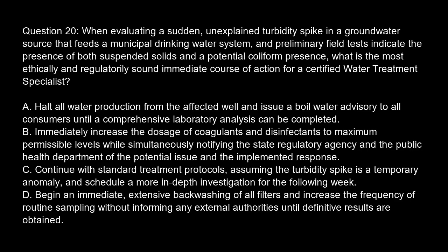Option A. Halt all water production from the affected well and issue a boil water advisory to all consumers until a comprehensive laboratory analysis can be completed. Option B. Immediately increase the dosage of coagulants and disinfectants to maximum permissible levels, while simultaneously notifying the state regulatory agency and the public health department of the potential issue and the implemented response.